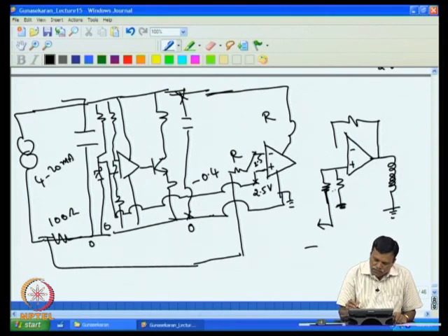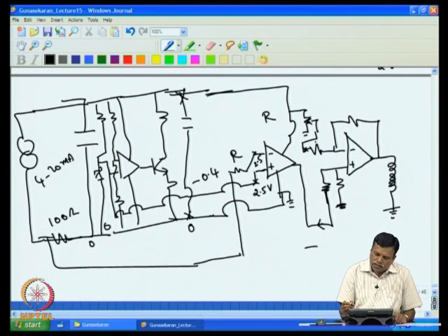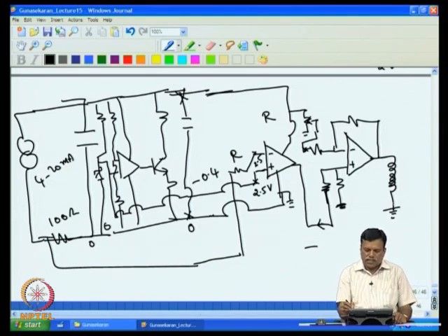So you got this. If there is more current and you want the actuator to move more, then I can give this one to the plus input, and then I can use this as V reference, or it can also be connected to supply, or it can be divided and connected to supply, so that you will get the difference between these two as an error, and the error will drive the actuator.